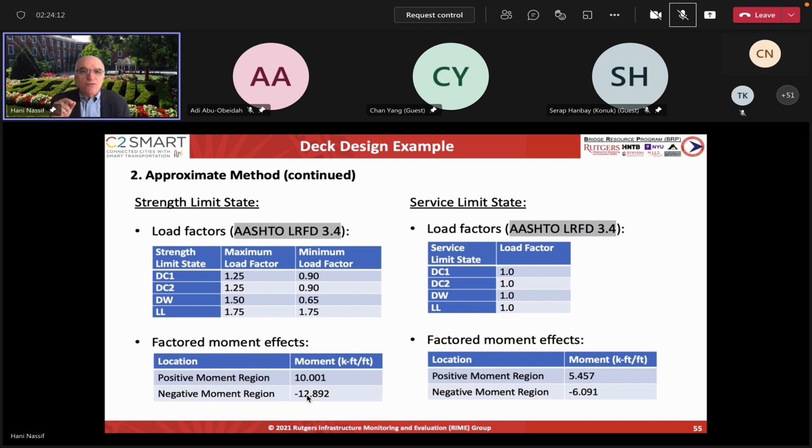We're assuming that the hairline crack width is 0.016 inches. That's the maximum crack width. And based on that crack width, and given the diameter of the bar and the cover, you come back and ask what the maximum spacing should be. So if a crack is forming, it doesn't go beyond 0.016.